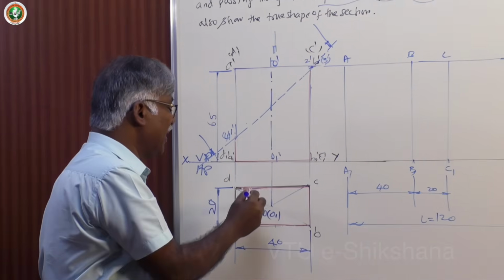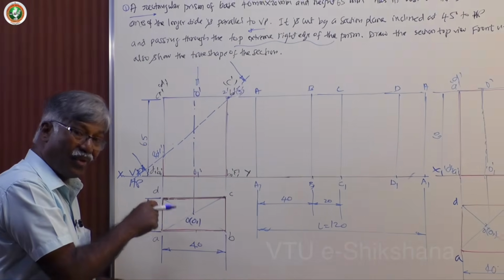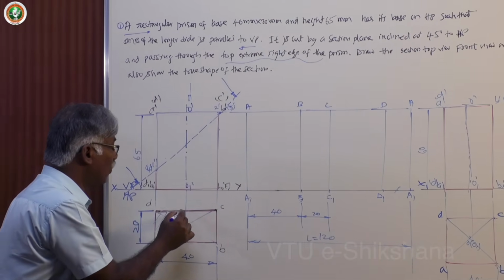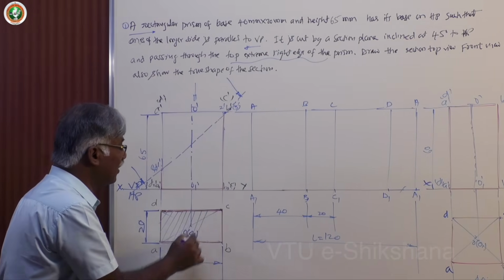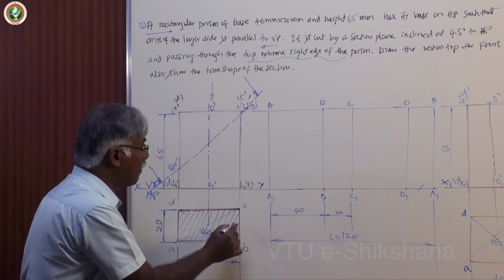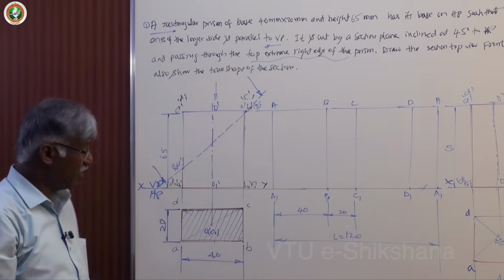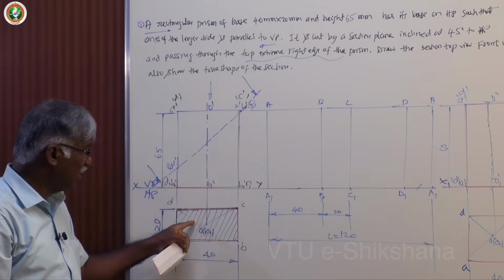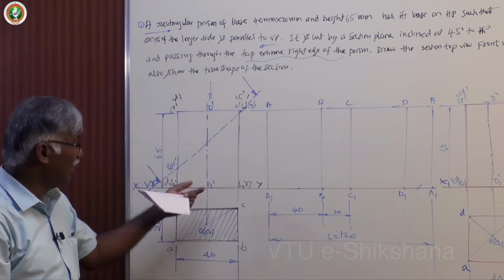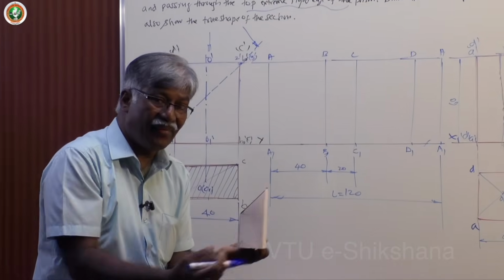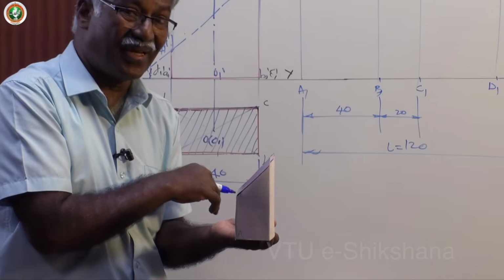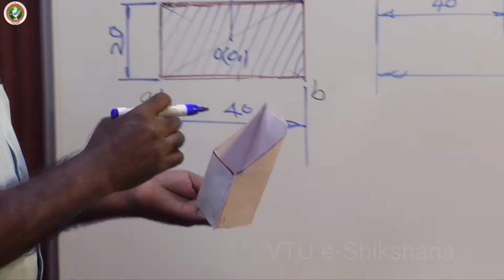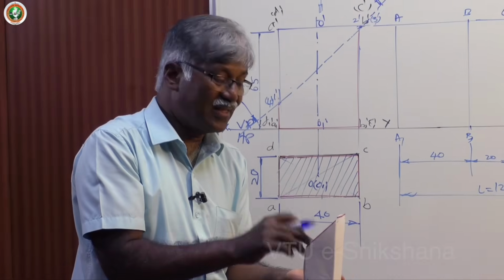The projection you have made here and you get the view from the top is this only. So you try to hatch it. Hatching is normally at 45 degrees with equal spacing. This is called hatching of the section portion. This is called the section. This is the sectional view. Why am I calling it sectional view? It is representing the section along with the remaining portion, but you cannot experience it in this particular case. You can experience that in pyramids, in the simple cases. Okay, because whatever is available is coinciding with the sides of the section only.